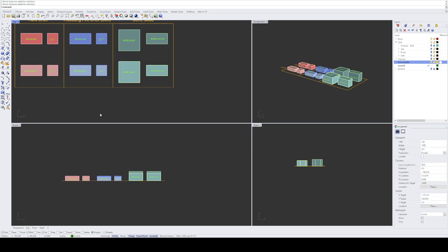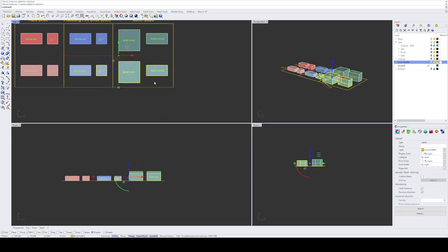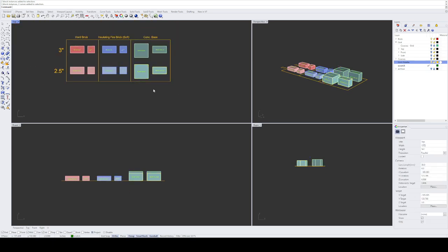So just see the difference here, right? If I go left to right, because I want to select just that big green 9 by 9 by 5, right? Whereas if I go right to left, anything I touch is going to select all of those things. So these four windows, they're all just windows onto the same set of objects. They're four different views.